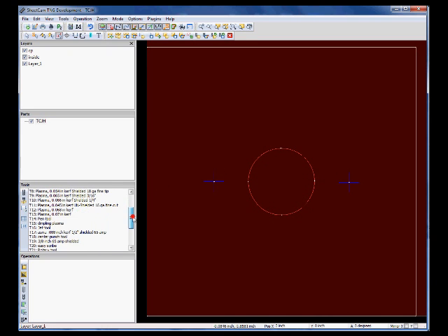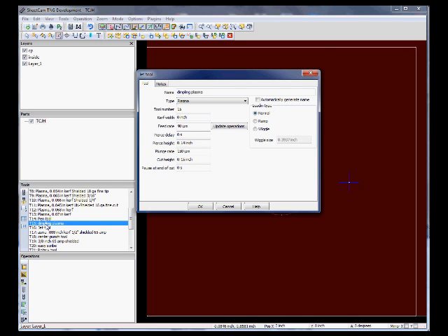I have a tool, dimpling plasma is what I called it. Kerf width is 0. Your feed rate doesn't really make any difference. Pierce delay is 0. Pierce height is 140 thousandths. Pierce rate is whatever, you don't really need cut height.